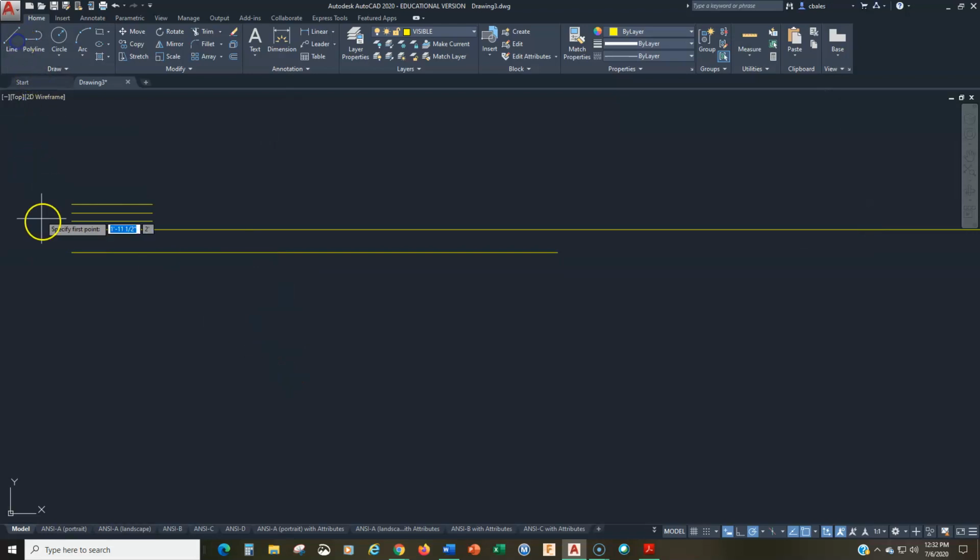Okay. Now, another option, we can do 3 apostrophe dash 6. Now, the dash is important. A space, remember, a space means the enter key. So if we do 3 apostrophe space 6, it's going to enter the 3 apostrophe because it's going to take that space bar as an enter. So we have to use the dash. 3 apostrophe dash 6. Yep.